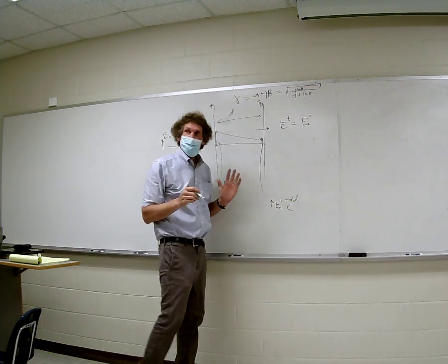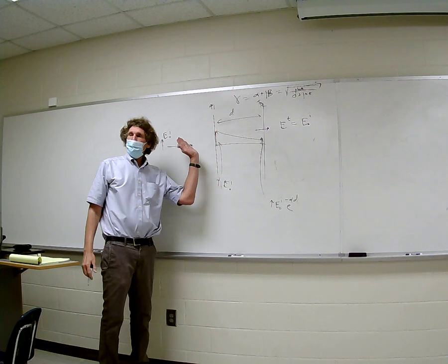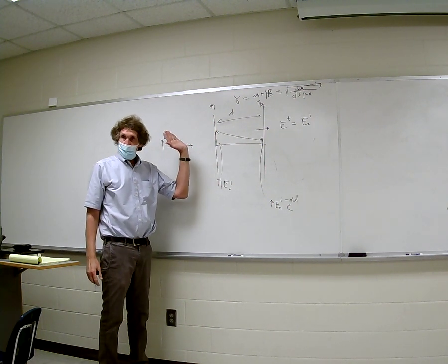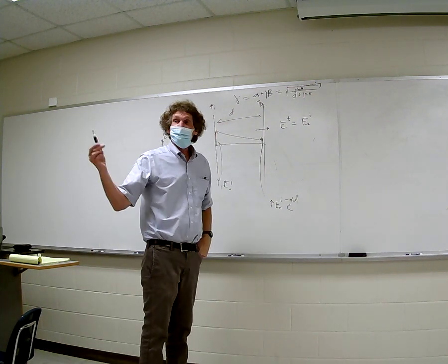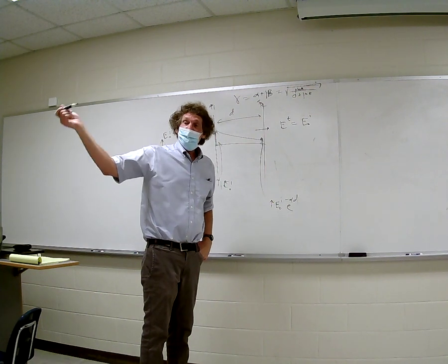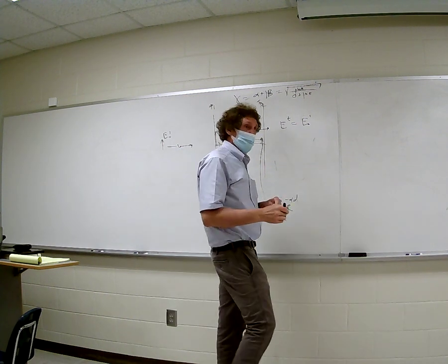Now again, I'm assuming this is normally incident. We talked about oblique incidence. It's a more complicated problem, but normal incidence is the way we think about it, because with oblique incidence the shielding effectiveness is greater. As the wave comes in at a non-normal angle, you get even greater reduction. So they always look at the worst case.